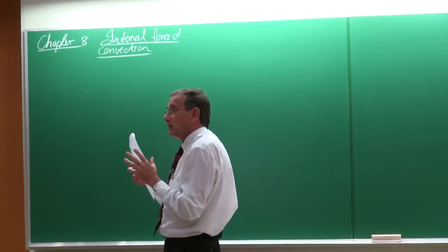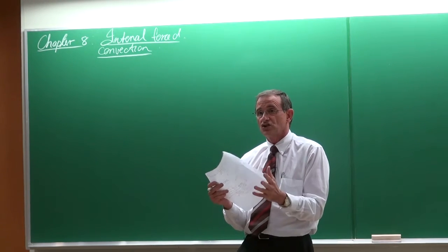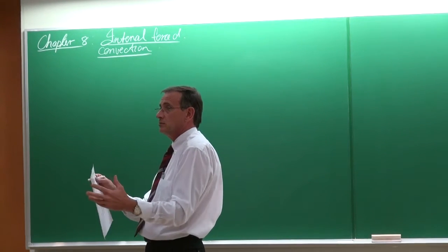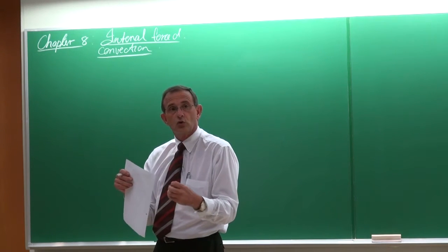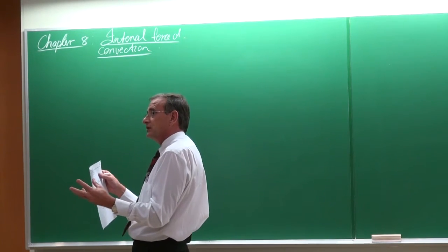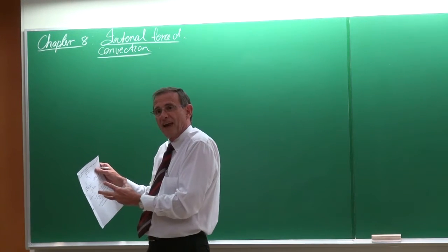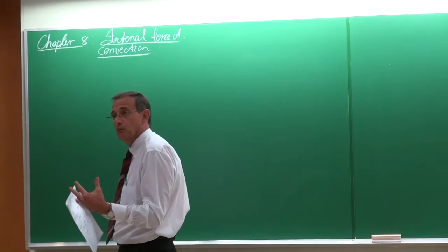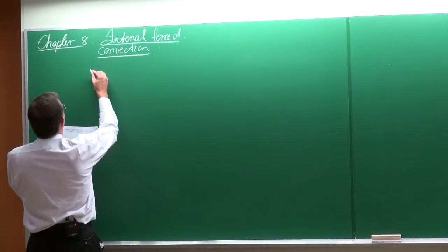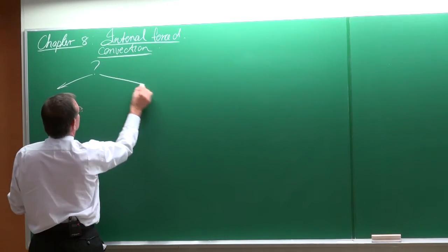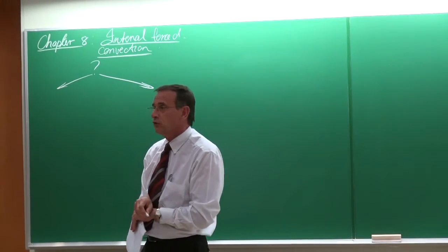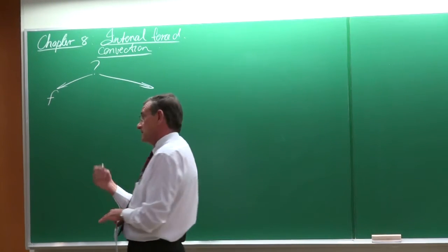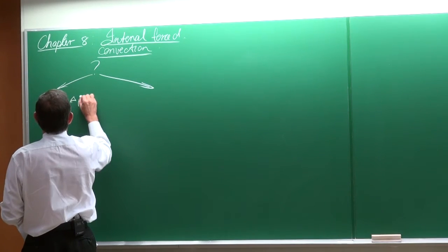Okay, now the thing is, when we design heat exchangers or any such things, then we are normally not only interested in the heat transfer, how many kilowatts we can transfer, but what is always associated with convection heat transfer is that we need a pump or a fan that drives the process for us. And therefore, the friction factors are just as important. So there are normally two things that we try to achieve when we look at internal forced convection. The first one is to get the friction factor, because if we can get the friction factor, then we can determine the pressure drop.